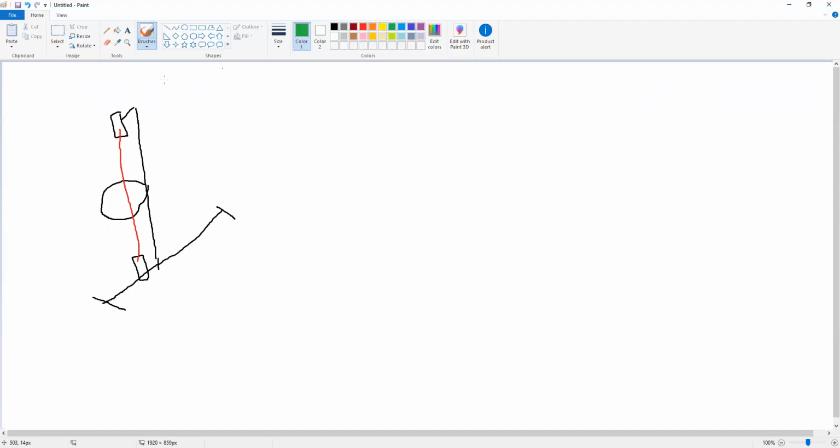How do we start testing? We just add the loads one by one, and as we mentioned, the loads are small weights. Each one of them is 5 Newton, and we have 10 again, like last week. So the maximum load we have is 50 Newton, so you will expect that all the 9 columns will fail before 50 Newton or at 50 Newton. If we apply the first load, the green load, the column will buckle a little bit, something like this, but not fail. Using a vernier caliper, we will measure the distance between the ring and the column, so this is delta 1. We will record this in a table.